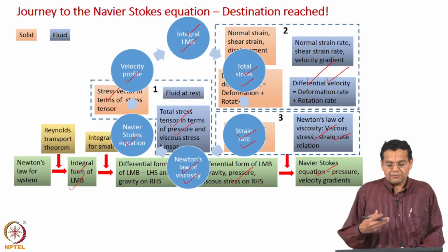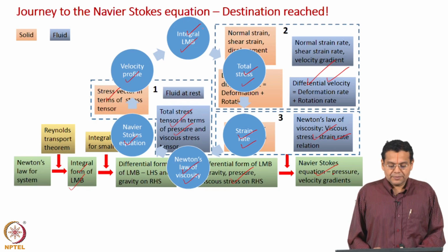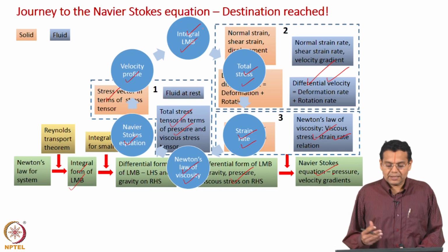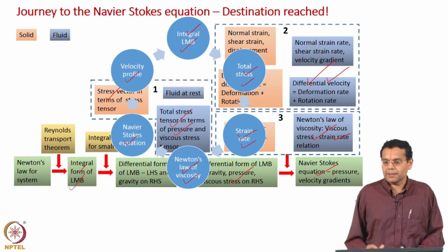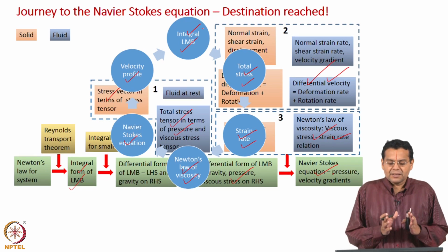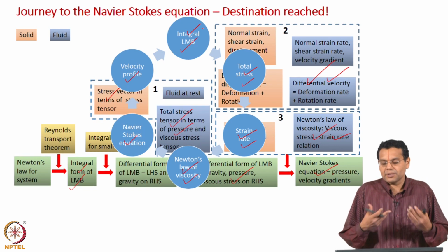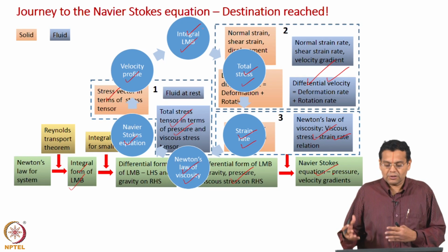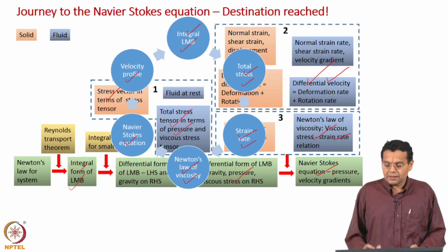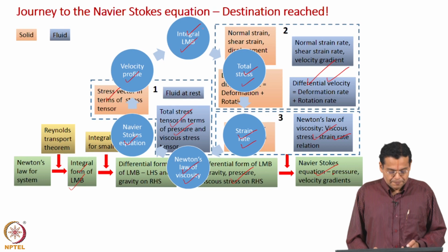Okay. When we came to the forward path, they were all led us to the derivation of Navier-Stokes. Now, we can understand why we really came through that particular path. They were all expressions, dou Vx by dou x, or dou Vy by dou x, or dou Vx by dou y, and then such a combination was strain rate tensor, components of strain rate tensor. But now we can all evaluate them in terms of values as well, in terms of the velocity profile. In terms of measurable values, you can evaluate them.